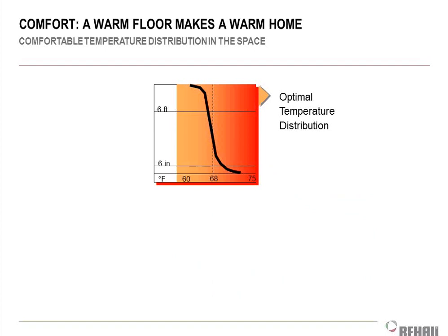Everybody probably knows air temperature is a big comfort driver, right? And you probably know humidity is a comfort driver. I'm sure you've talked about both of those things with your clients before, right? But there's several other factors involved, not just dry bulb temperature and humidity, but also the mean radiant temperature is a factor in that formula for ASHRAE Standard 55. Air movement is a factor, clothing level, activity level. There's several things that determine whether you're going to be thermally comfortable or not.